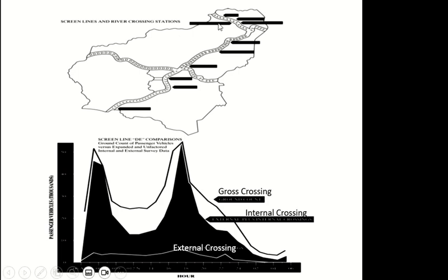You can see we have two areas here, and between the two areas we have a river. Just imagine, you have a river. So it happens in places like Amsterdam, and there's a city, I believe it's Venice in Italy. These cities have rivers in between their districts of the same city. So here they can make the river the screen line. And then you can have others as well. You can have a mountain range. You can even have a highway between the two areas. Whatever you feel is the line between the two areas, you can make it your screen line. And if you have to cross it from a road, then you cross it at the mid block, not at the intersection. You can move it a little bit forward or backward just to make sure it crosses at the mid blocks.